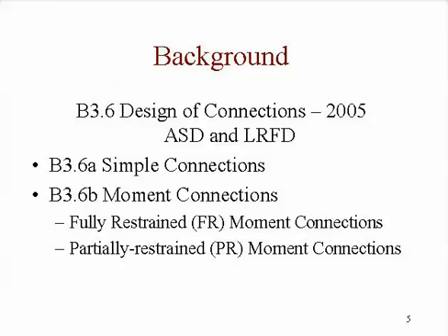With this specification now, the committee realized that it was kind of a stretch to only consider simple connections as a special case of partially restrained. And so in section B3.6a, the specification now defines simple connections. And in B3.6b, it defines moment connections, and under moment connections, fully restrained and partially restrained.